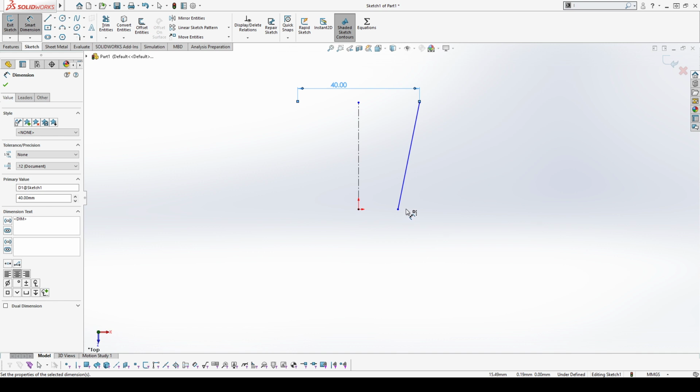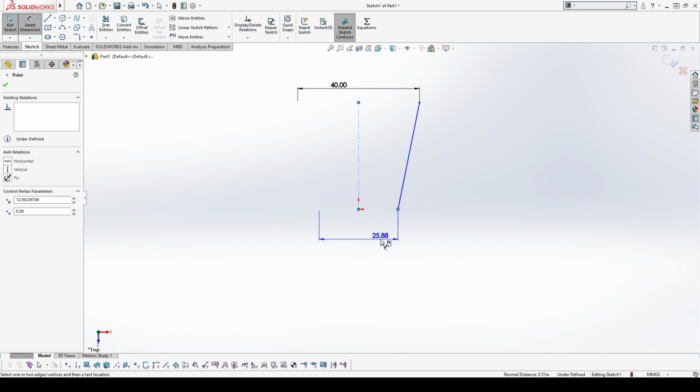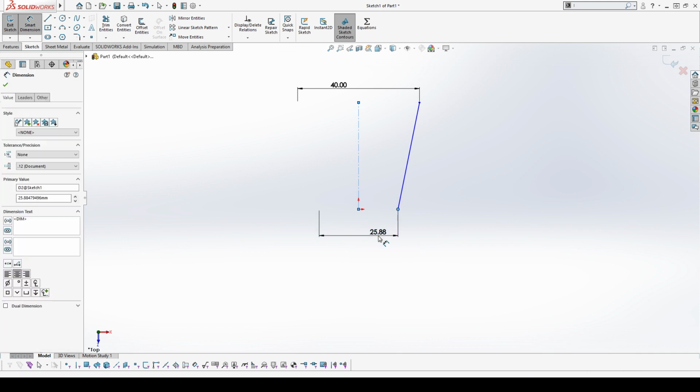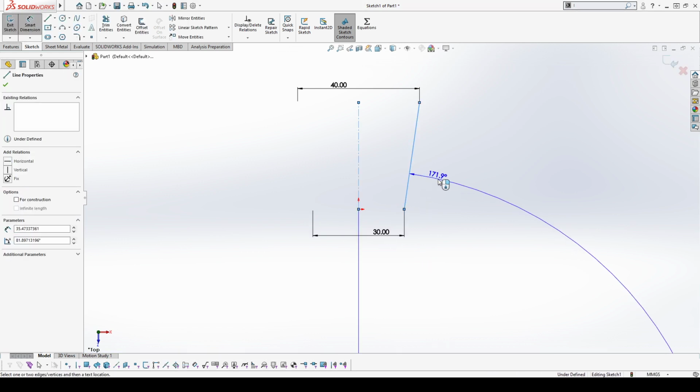And then one of the other things that SolidWorks does, if you look at my cursor, it has the dimension icon right next to it, as well as D and a construction line. So it's automatically going to add in any other dimensions that I want. As I go through here, it's automatically going to assume that I want to do a diameter dimension around that center line that I selected already. And that is the case, 30 millimeters.